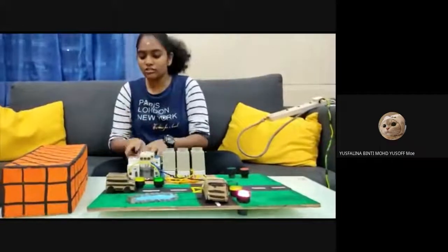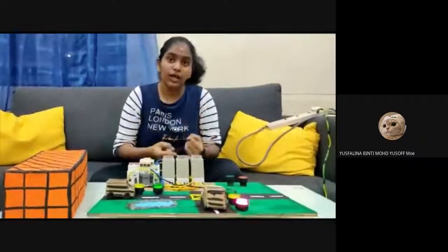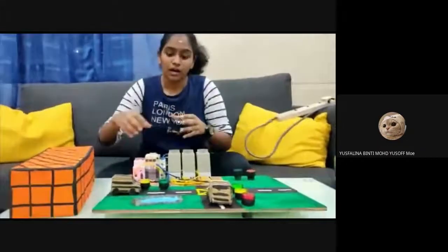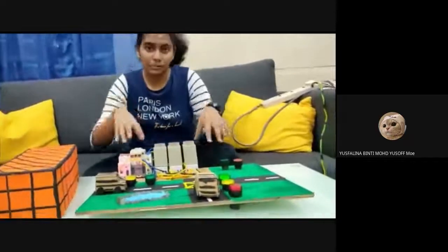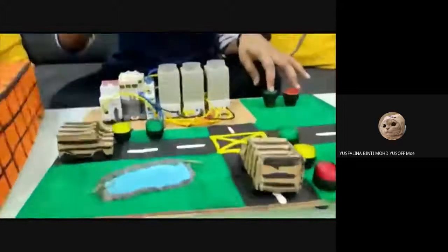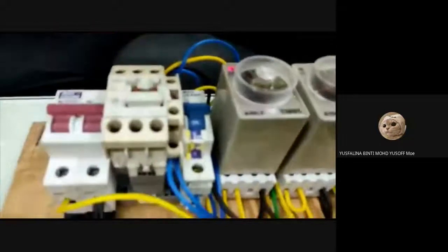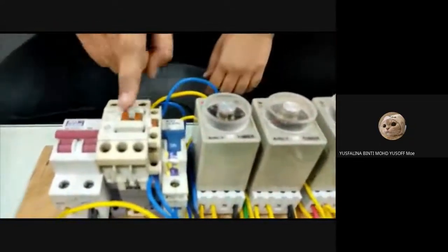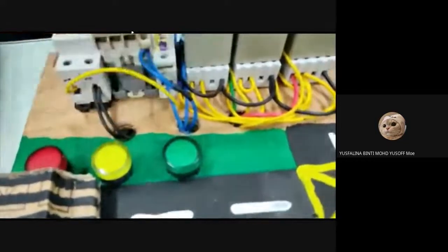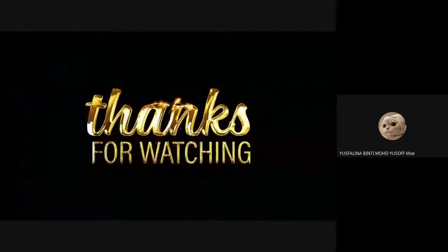Now we are going to loop this neutral wire and live wire to all these components and make these lights work in order. So this is the main part that I'm going to talk about. Let's say I'm switching it off, and when I'm switching it on, you can see that this button goes in, and when I'm switching it off, you can see that this button goes up. So here are the live wire and the neutral wire that I've looped to the MCB. This MCB also acts for safety purposes.